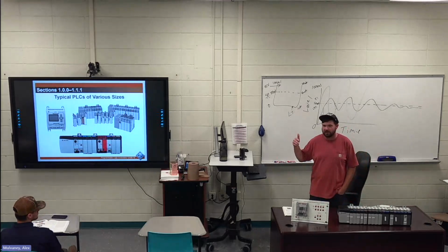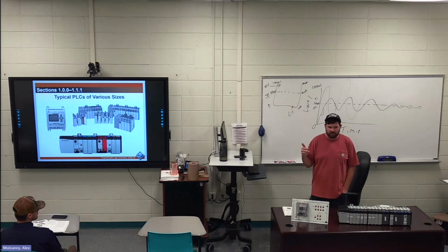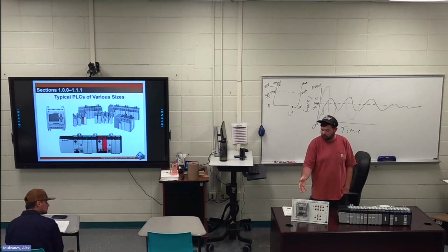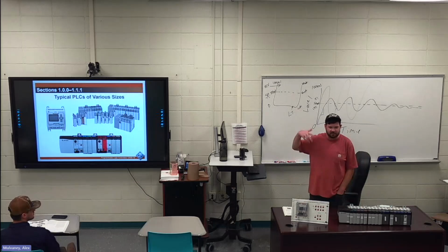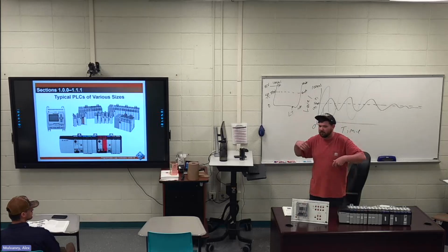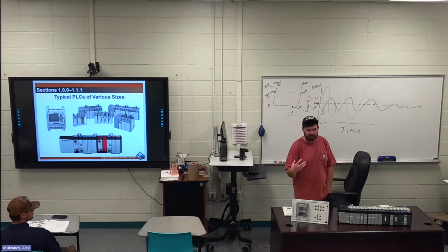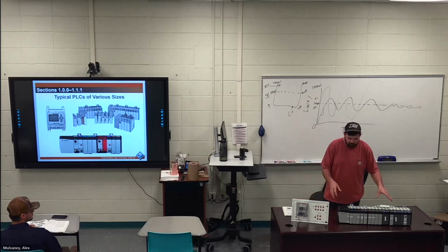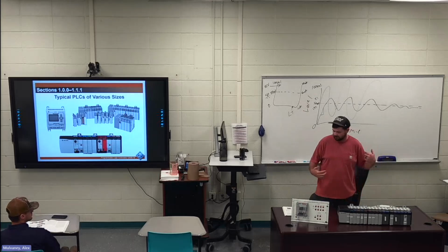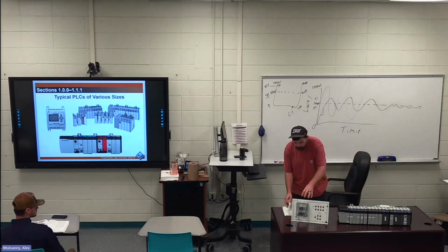So there's a large variety. Like, you know what a lift station is around here, moving stuff around the parish. Those have micro PLCs. I've opened up one of the cabinets before, and those have micro PLCs that don't have to have a computer attached to them. They just put the program in there and it works, with floats and stuff on it. So digital inputs: when it fills up, it turns a pump on, it goes down, it turns the pump off, instead of having contactors. So they would use something like this for a small system like that, whereas a big company would use something like this for all the systems that they have, right? So good for small systems.